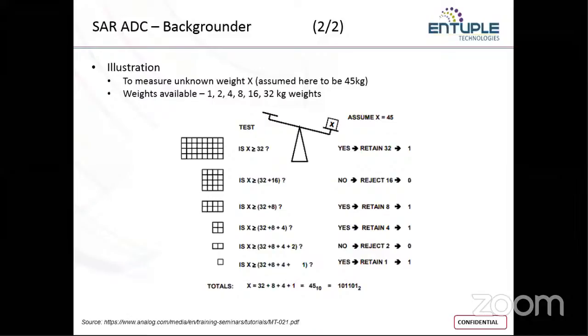If you are working on a 4-bit ADC based on successive approximation register, the MSB will be set to 1 first. MSB will be initially set to 1, and the particular value of voltage will be compared to the analog voltage.